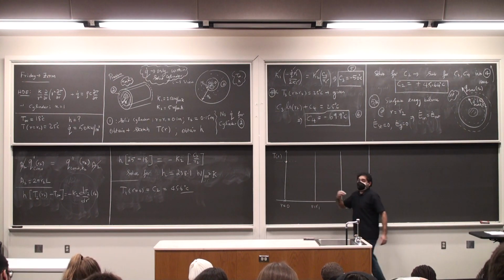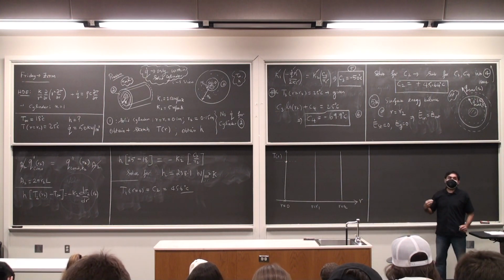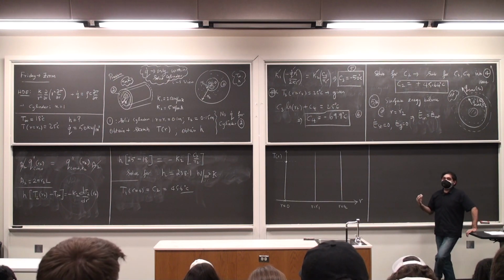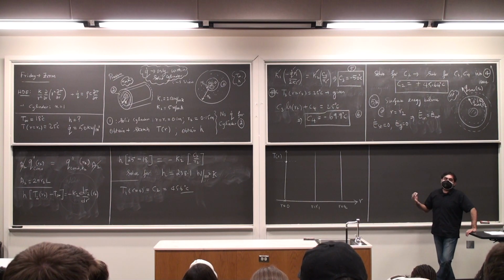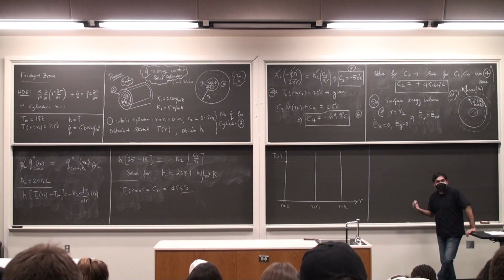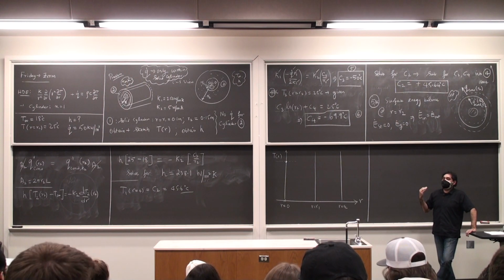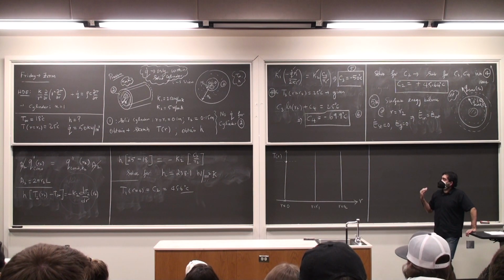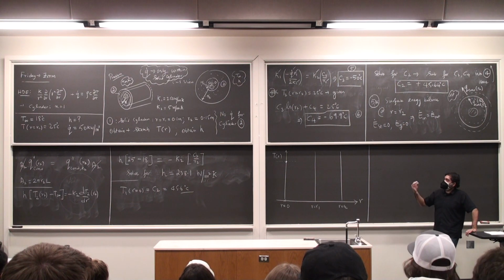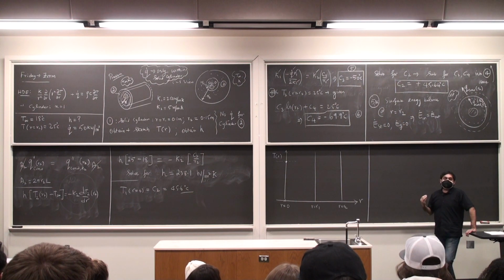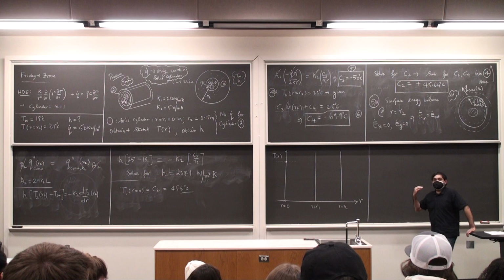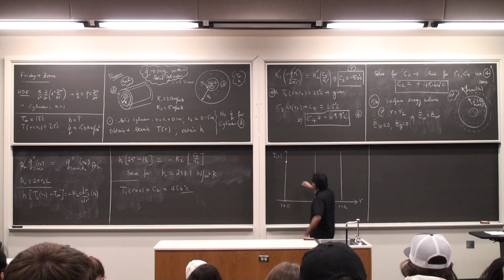I have volumetric energy generation, constant. Because I'm looking at a solid cylinder, I don't need to worry about the logarithmic terms. So this is just going to be a quadratic profile. And since the temperature at R1 is less than the temperature at R equals 0, I have to come down in a parabolic fashion in the following manner.